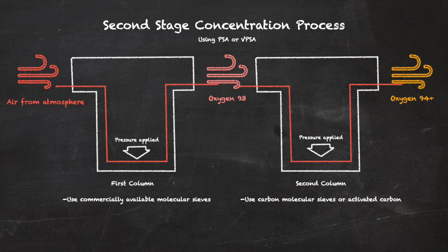However, with this high level of purity comes other problems. The oxygen recovery, or the oxygen purity going in versus the oxygen purity going out, on the second stage is low. Consider the single stage will go from around 20% purity from the air we breathe to around 93% through the one concentrating process. This results in a high oxygen recovery ratio. Second stage will concentrate from around 93 to 99% purity. Thus, a second stage concentrator is not as effective as a single stage concentrator.